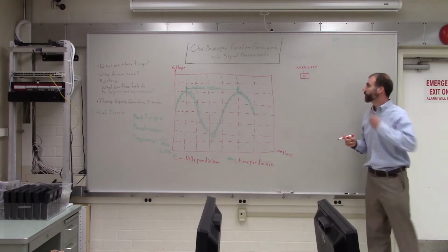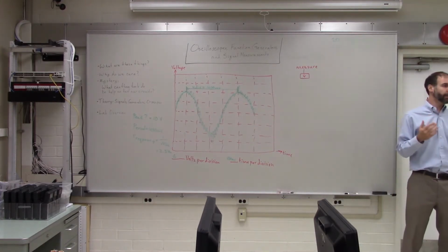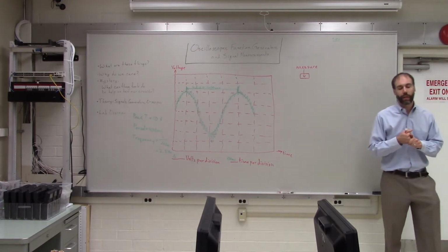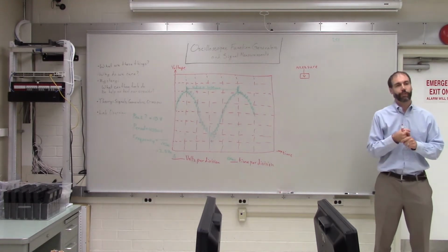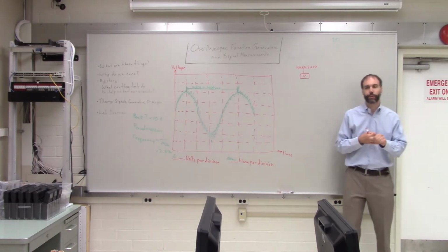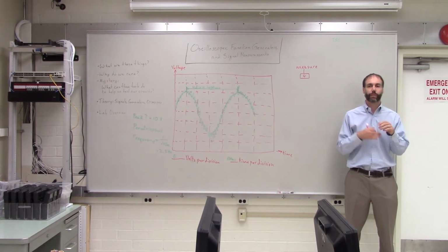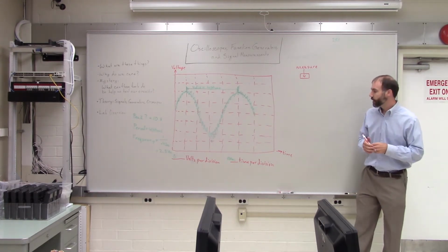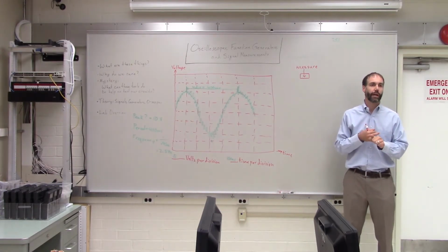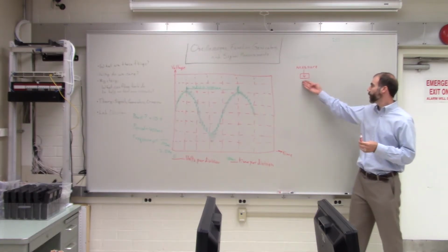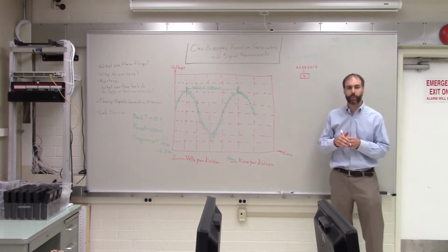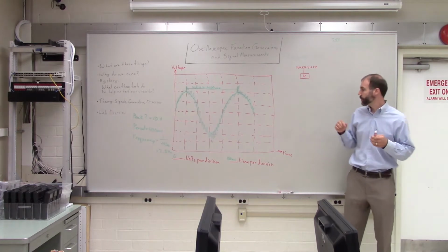And when you push that, that's going to bring up a menu that has lots of different measurements in it. And then you can choose which one you want. So you can choose things like peak amplitude or peak-to-peak amplitude, or RMS amplitude, or frequency, or period, or lots of others. They actually have some related to duty cycle as well. So they have time high, things like that. So if you push this measure button, you can scroll through those different options and then choose the one that you want. And you can have many different measurements up on the screen at the same time.